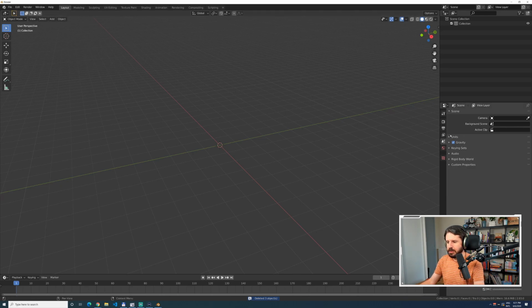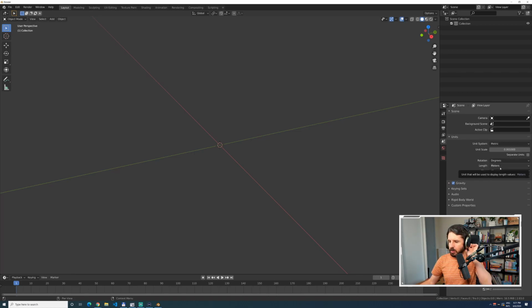Now, let's make sure that the scene is using the proper units by default. I think that the default unit in Blender is 1 equals 1 meter. So that's not good for me. I'd rather have my default scale to be in millimeters, and the way length dimensions are being displayed, I want that to be millimeters as well. And I will double check every time I import some objects, etc. You need to make sure that your units match.